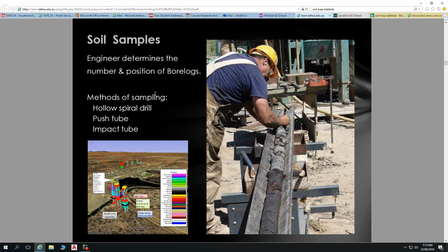What you're going to want to do on site? So typically your soil sampler. Well, so what we always did with the engineering office, what my job was a lot, was to produce site plans ready for the soil sampler to take out with them. So they can go measure where those borehole locations are, mark those on the plans, and they come back and I draw them up. That's going to look a lot like this.